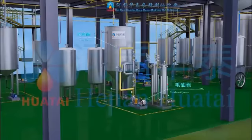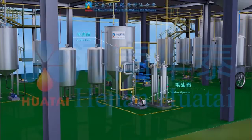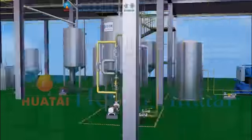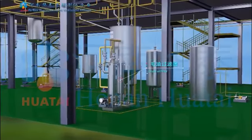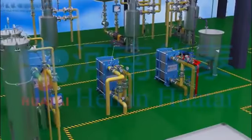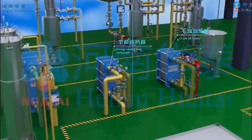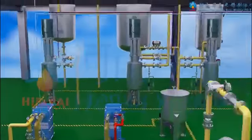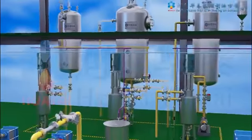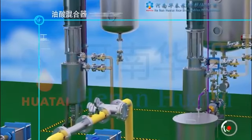The extracted crude oil goes into the refining plant and is temporarily stored in the crude oil tank. The crude oil pump pumps the oil into the crude oil filter. Filtered oil goes into the energy-saving heat exchanger, where it exchanges heat with the dry oil, and is then sent to the crude oil heater. After the temperature rise, the crude oil goes into the oil-acid mixer.